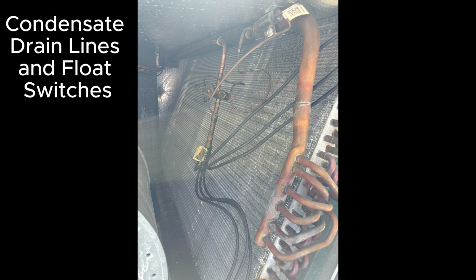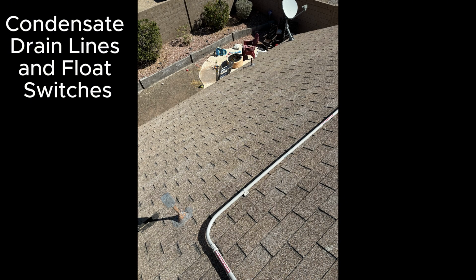When humidity comes across it, it condenses into water, hits the black drain pan on the bottom, and then flows through PVC pipe. That PVC pipe is called a condensate drain line, and it's normal for water to flow through there and to the exterior of the home. We want the condensate drain line to exit somewhere where it will not be a hassle to the homeowners or to anyone. Often you just walk by it, you have no idea what it is, but it's dripping water a lot.